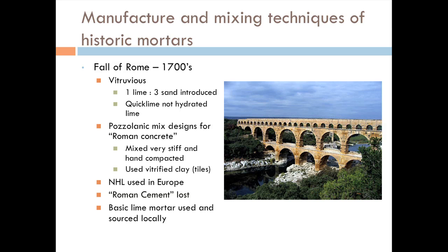And I should mention that these pozzolans, if you add water to them, they're not going to do anything. They're not going to do a darn thing. They only chemically react with lime and, to some degree, cement. And they've also found natural hydraulic limes in Britain and France. They've found natural deposits there that we actually still use today around the world.